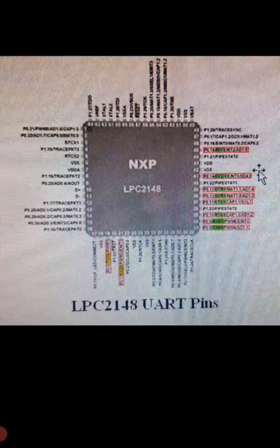This value must be 16 times the desired baud rate, whereas the 0x000 value is treated like the 0x001 value. Division by 0 is not allowed. The divisor latch access bit in U0LCR must be 1 in order to access the UART0 divisor latch.